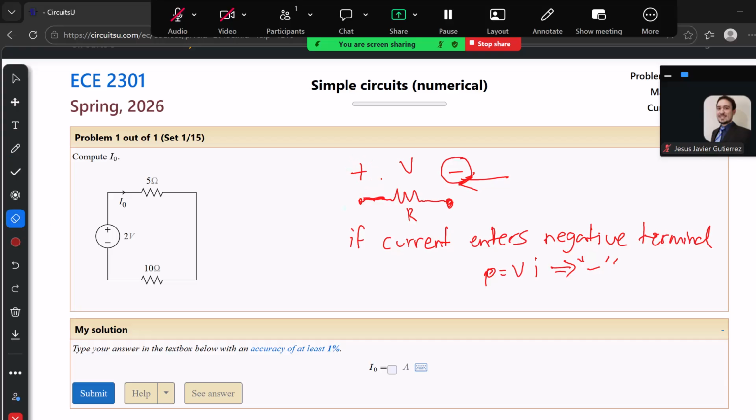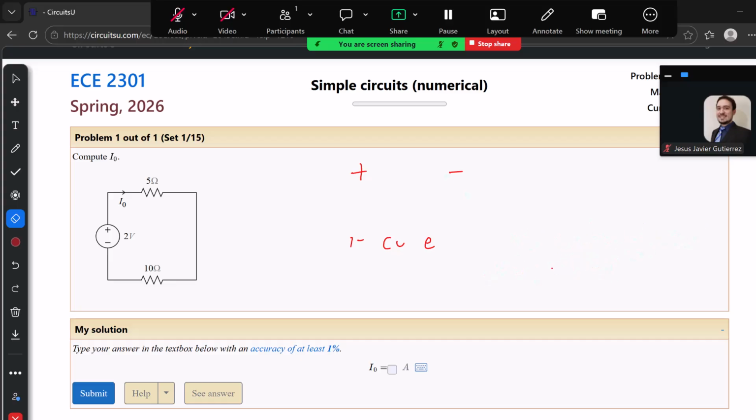Current sources and voltage sources are a little bit more complex than resistors, but as long as you keep to the passive sign convention, you will have no problem. The way I use the convention is that, let's say we have a plus and minus voltage here, and here we have the two terminals. Then I know, because of the polarity of the voltage, that my negative sign will be on this terminal and the positive will be on this terminal.